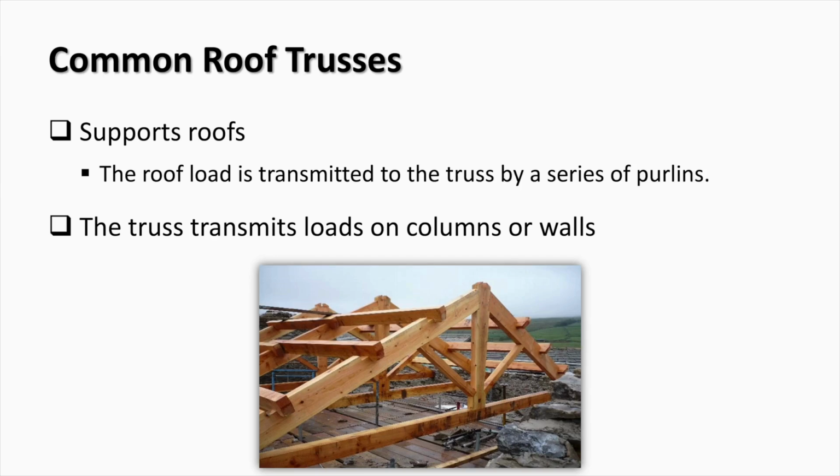Trusses are widely used to support roofs. Here you can see a Fink roof truss. In this case, the roof load is transmitted to this truss through a series of purlins. Then, the truss transmits loads onto the columns or walls.